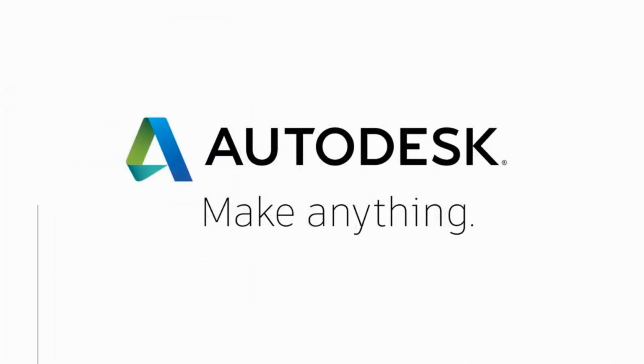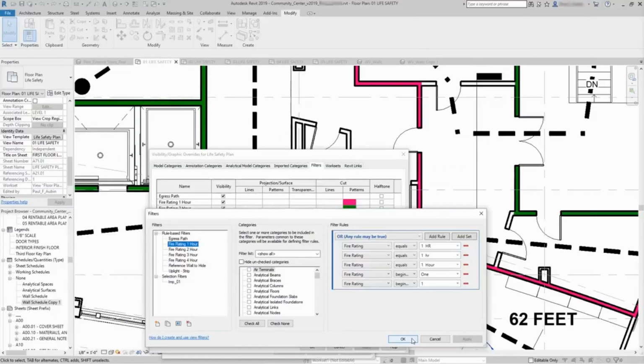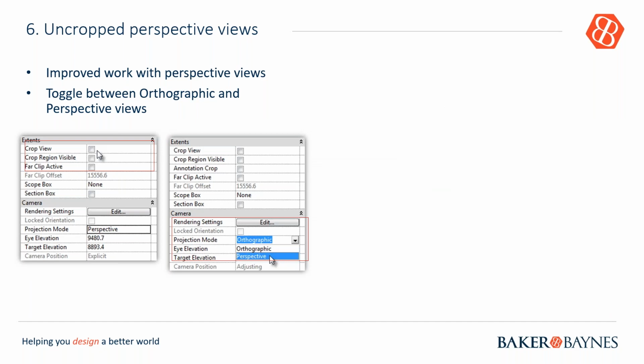Okay, so you see how the filter command has been improved in 2019. Next one, we're going to look at uncropped perspective. In terms of the uncropped perspective views, you'll see that 3D views in Revit now support orthographic as well as perspective projections.